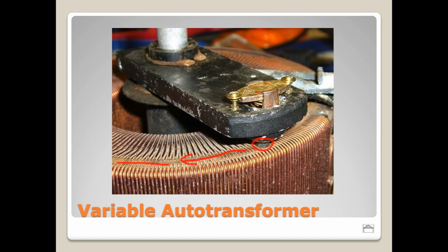Rather than reducing the voltage, they actually turn the voltage off for a short duration, depending on how bright you want it to be, right? So if you want it at full brightness, it just never turns the voltage off. If you want it at half brightness, it's going to turn the voltage off for half of the given cycle that it's running through, the rate that it's switching on and off. It's going to turn off the voltage for half the time, and then it's going to turn the voltage back on for another half of the time.